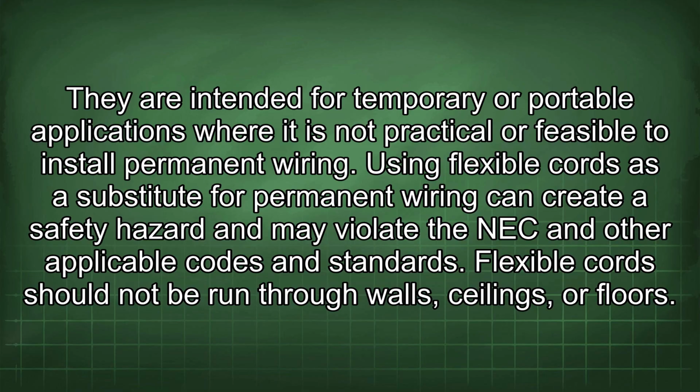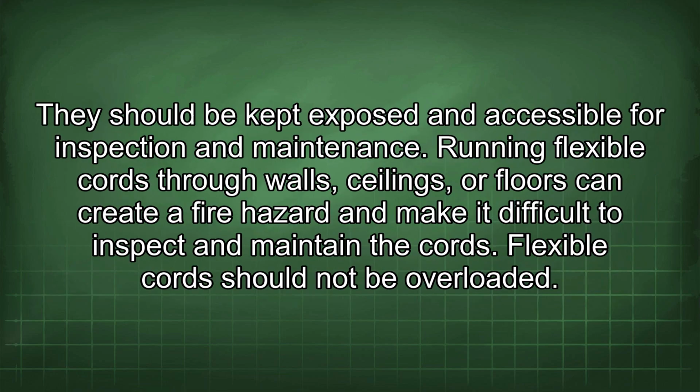Flexible cords should not be run through walls, ceilings, or floors. They should be kept exposed and accessible for inspection and maintenance. Running flexible cords through walls, ceilings, or floors can create a fire hazard and make it difficult to inspect and maintain the cords.